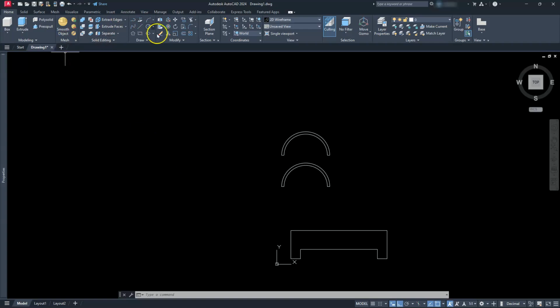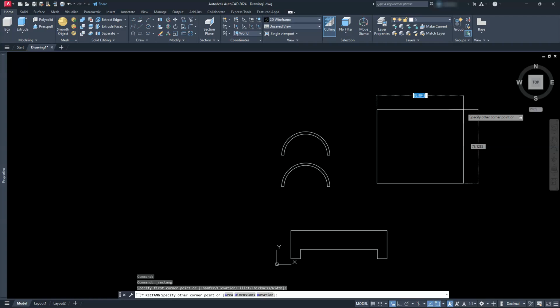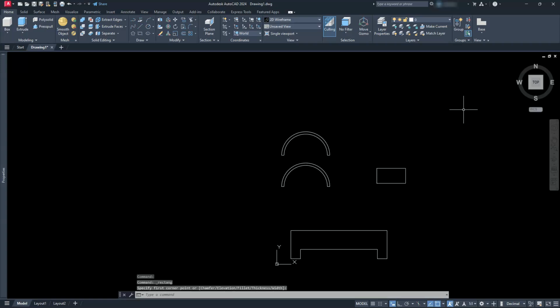So I'll go ahead and create a rectangle. Rectangle is located here. Let's click here. And then the numbers are the coordinates I'm going to need. It should be 30 going in the X direction, comma, and then how tall. This number has to be greater than 15. Well, it has to be 15 or greater. If I make it 15, that's okay, but I always like to leave myself a little bit more cushion. So let's make that number 16. What that does is eliminate any chances of it making a skin or some kind of super thin part that it leaves on there.